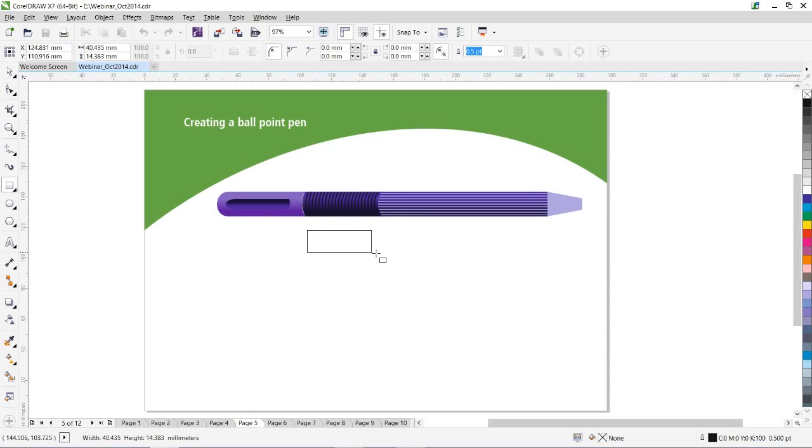Okay, I start drawing with a rectangle. Control and space bar converts my cursor to the last used tool. Now I am transforming this rectangle, and with a right mouse button click before leaving my normal button, I duplicate this. Same thing here, duplicate with right mouse button click.